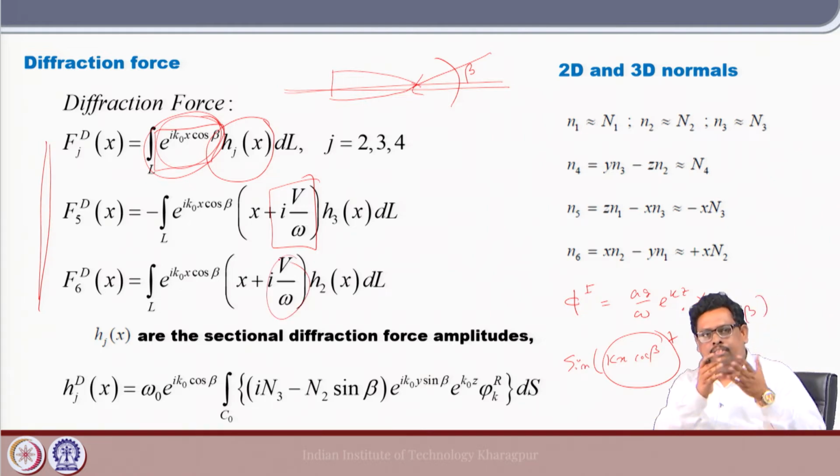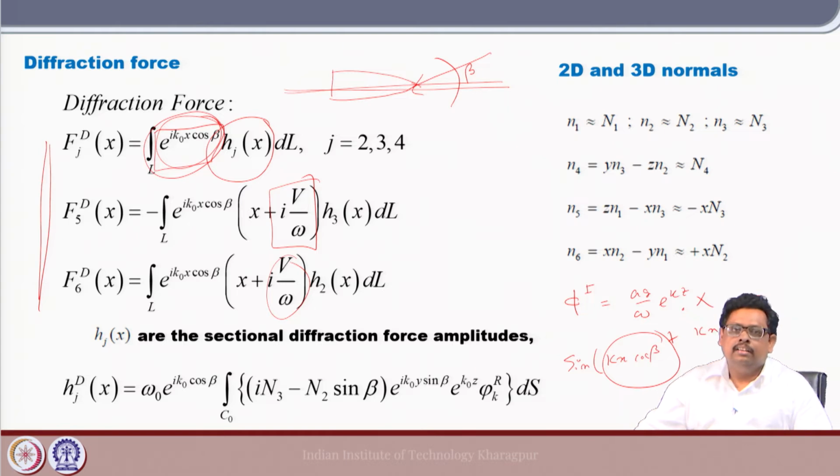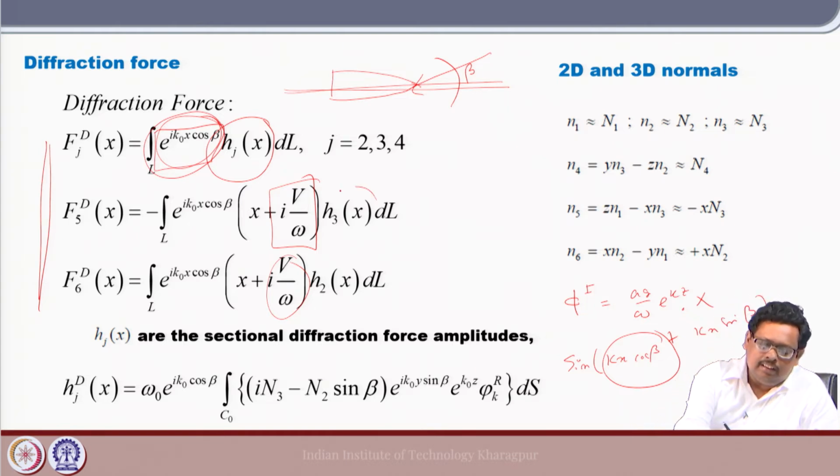If you follow the Faltinsen paper, I mean the classical STF paper, all these discussions are there, but here our intention is how to get this sectional diffraction force.